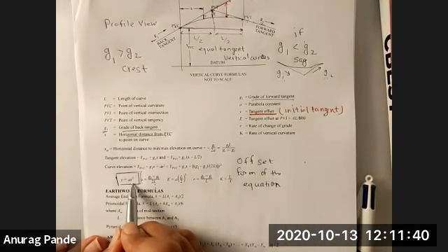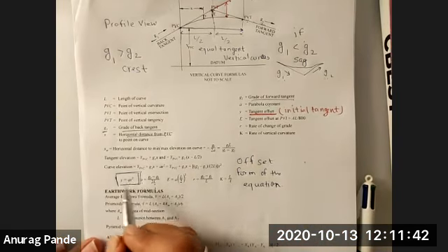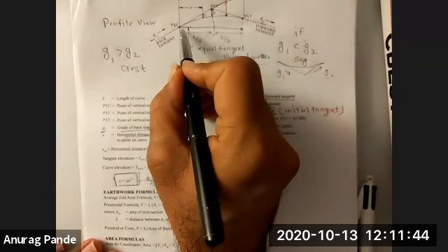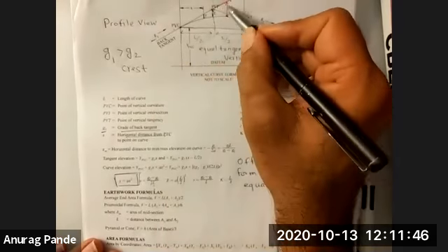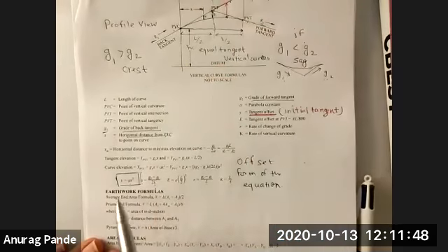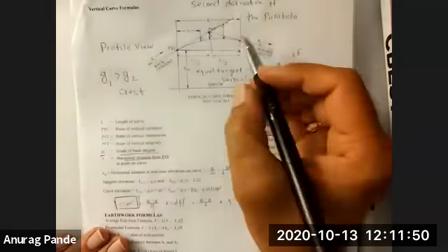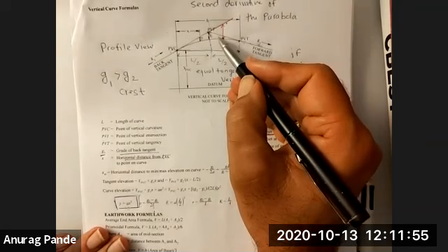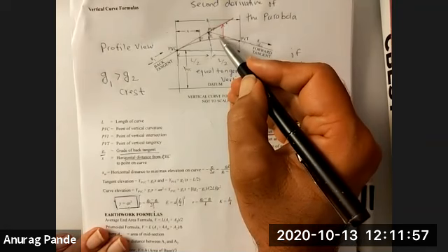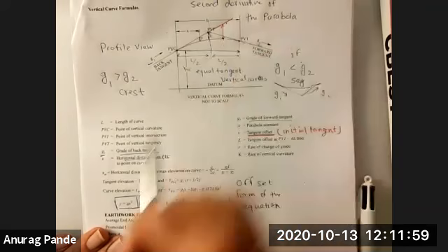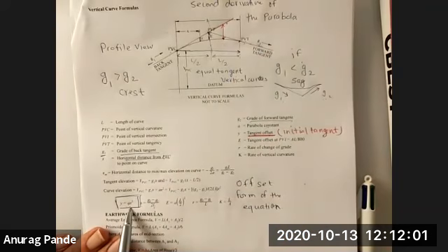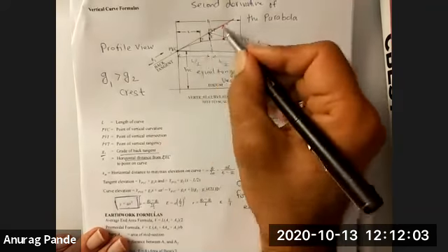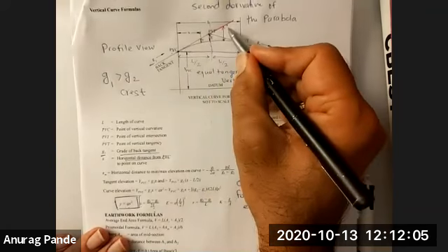A is a constant, and x squared is always a positive number. So as you move forward, this distance always has to increase. That is your clue that if you measure from the final tangent, you're making a mistake, because that value would start to go down beyond the PVI. According to this formula, it never decreases. It always increases. So always define that from the initial tangent.